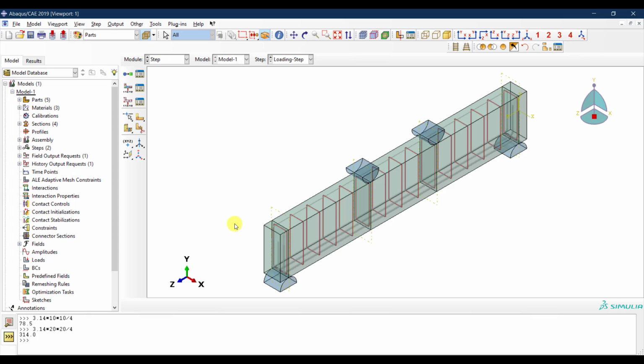It's a little bit fast, but I think the dynamic effects will not be substantial in this case, but we could go slower, of course. I'm not doing, as you notice, no mass scaling, nothing of these sorts. Again, this is a last resort thing. You can refer to the other videos that we have on how to use an explicit analysis solver.